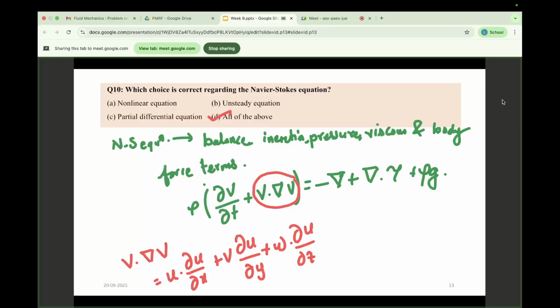Okay, so this is the basic. This tau has a certain formula. I cannot recall this formula right now. This is the stress tensor. This viscous stress tensor has a specific formula in terms of mu and all these things. So what do we know, what is tau? Tau is mu into du by dy, which is this one.